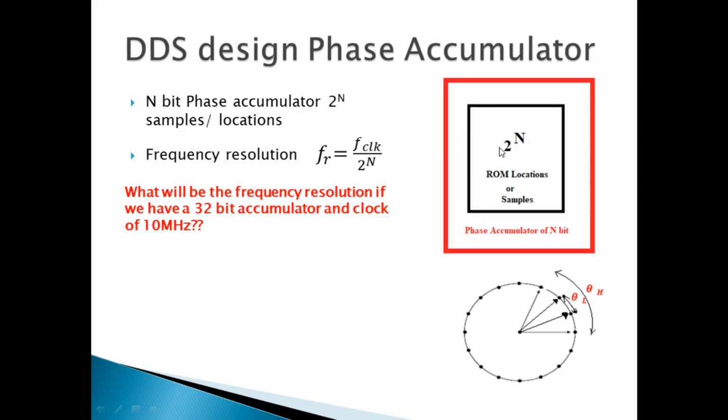So, what is going to be the frequency resolution that I would get from this synthesizer? It depends upon the bit size, the size of the phase accumulator. Of course, it depends upon that.